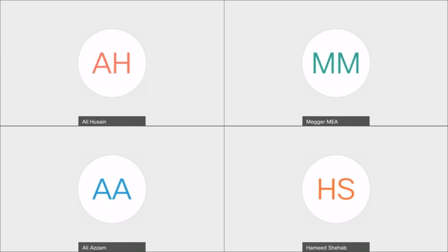Thank you for that question. The case he is referring to is that in a dead tank circuit breaker, we will usually have what they call a bushing attached CT in this dead tank. This is to reduce the manufacturing cost and also make the footprint less, so you don't have an outside CT as well and all the insulation towards it as well. So in this case, you still can do the contact resistance test for the CT.